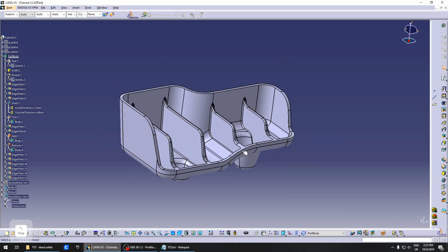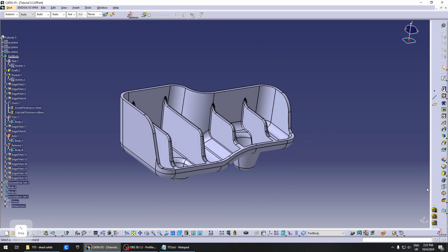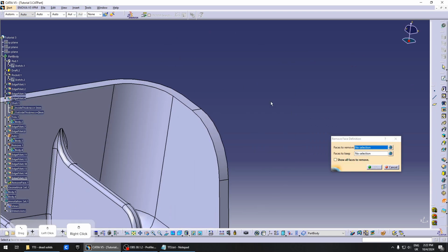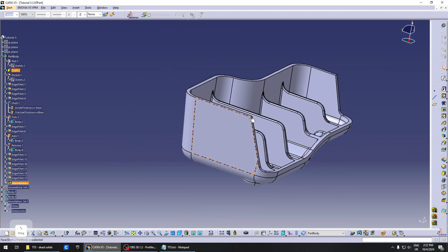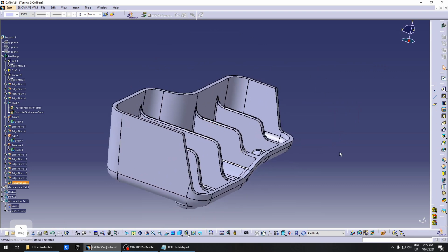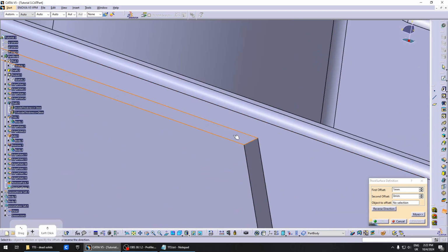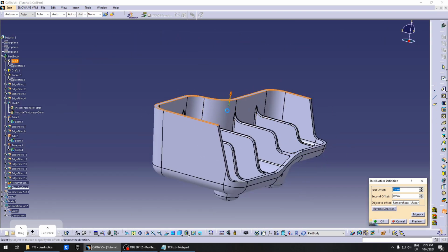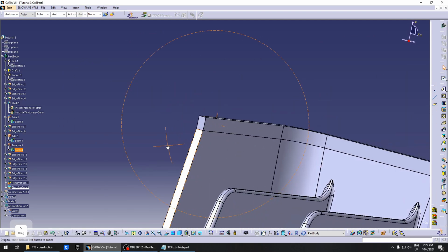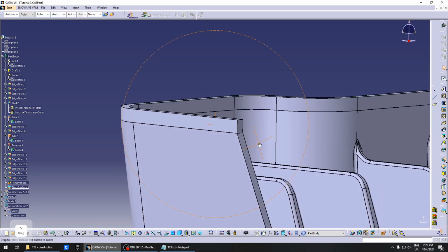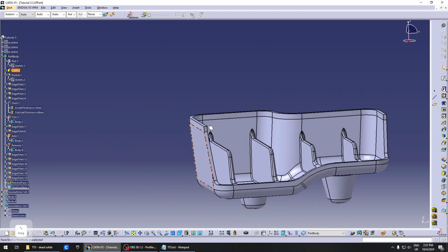So in order to increase the height of the part, what we would need to do is first remove the radius, so that way we separate the surface. We want to extend this one, and now you have a command called thick surface, this one, which would be the wrong one to use, because let me show you what happens if you put this, let's say 5 millimeters. You end up with like a little border on the part that just goes straight in one direction.